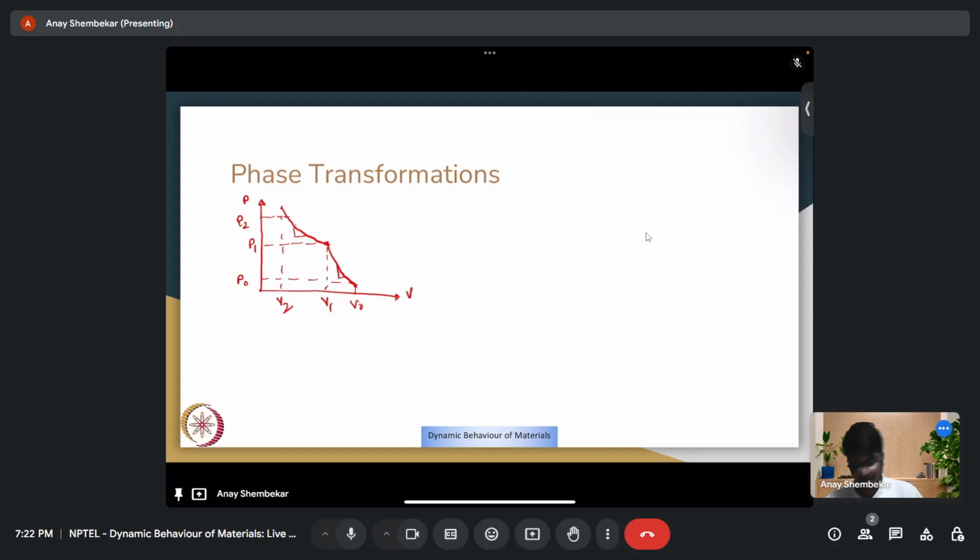Right. So we are concerned here with two shock fronts. Because there is a discontinuity, you could have two shock fronts coming up, and we are concerned about how stable it looks. If I draw a pressure versus distance plot, how the pressure profile looks at different distances inside the material would look something like this. Part of release wave, part shock wave S2 going down, shock wave S1.